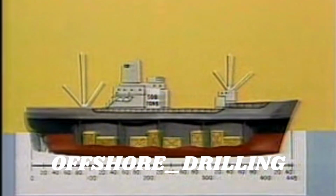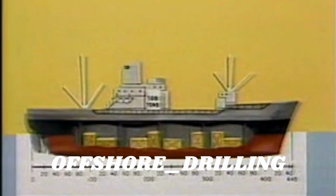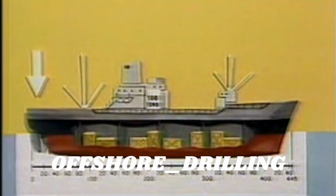In our problem, if we shift 500 tons of cargo from a forward location 100 feet aft to another location, we would produce a moment of 50,000 foot-tons. Divide this by an MT1 of 1,000 foot-tons per inch, and we obtain a change of trim of 50 inches. This 50-inch change will be divided equally between the bow and the stern. In other words, the bow will rise 25 inches and the stern will submerge 25 inches.